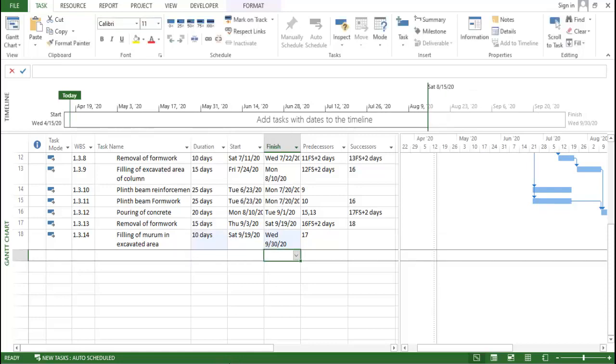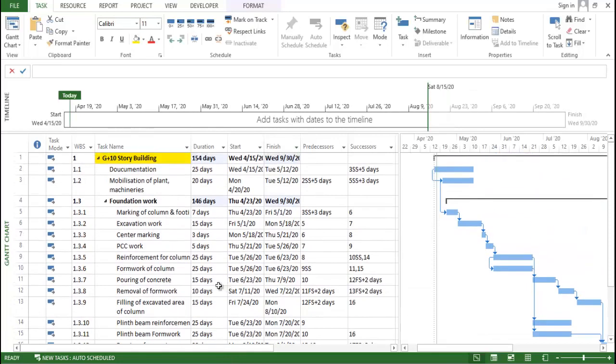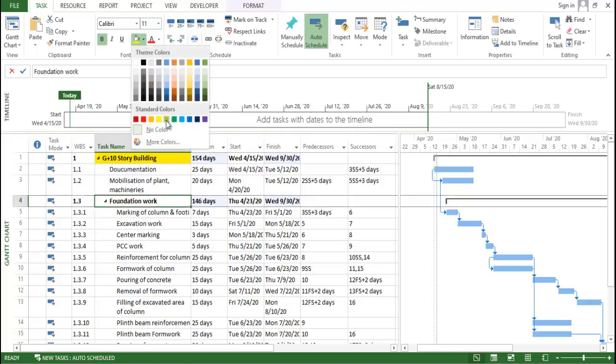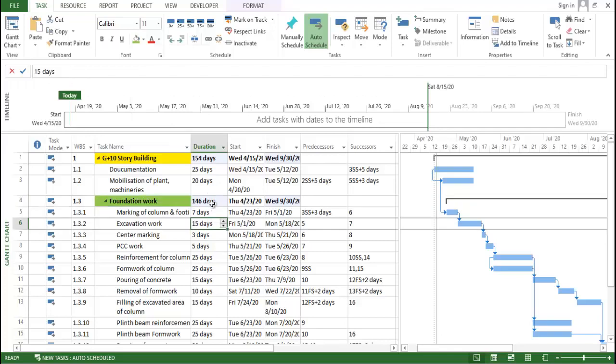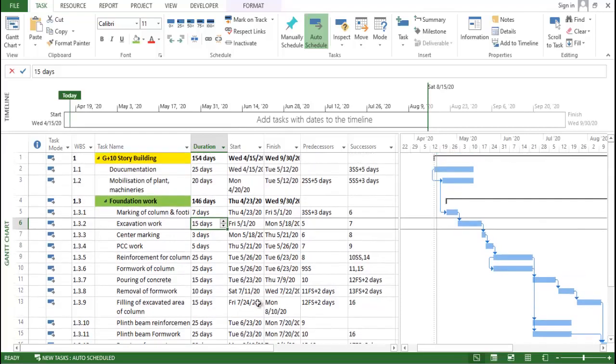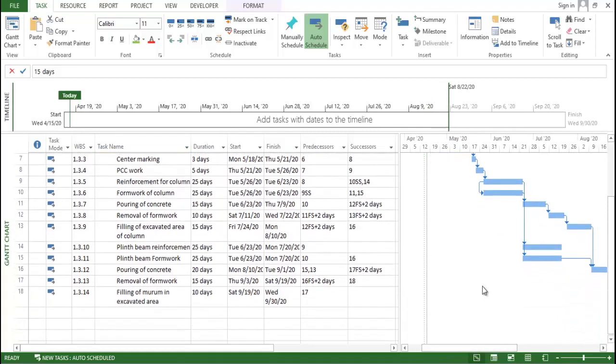So you can see, guys, if I come to the top portion, remember, you need not add any particular duration over here. These are automatic durations, because your tasks are auto generated. So what we have to do is put a task, put the duration and the link. These should be properly calculated. Now you can see all these things are properly calculated and defined here.